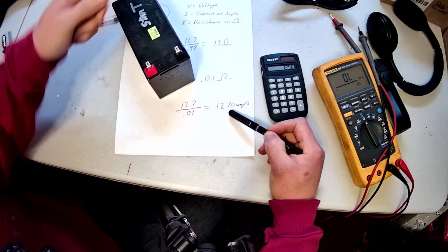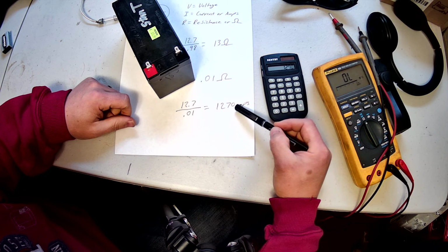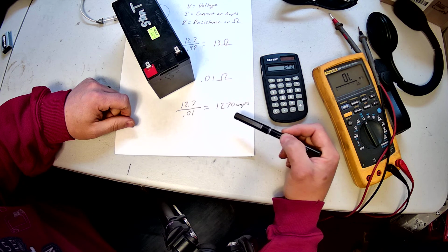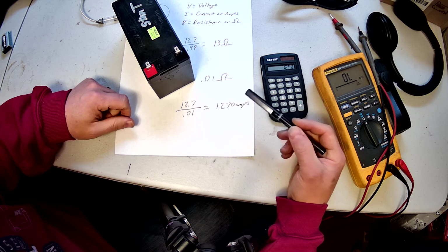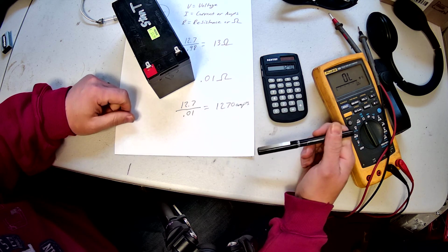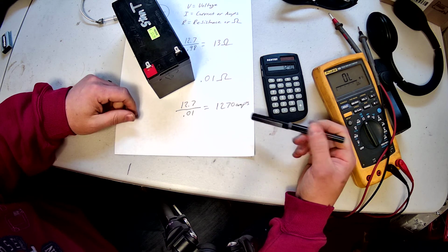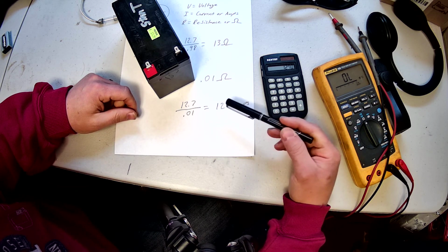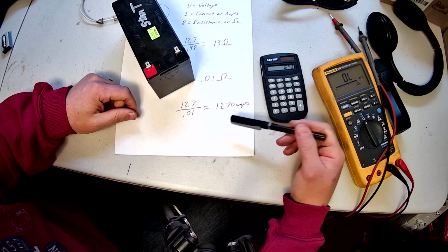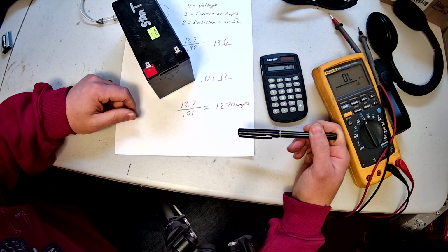And if you were to put that wrench across those terminals, you're basically going to pull that much amperage through there, which is a lot of energy, and you're going to get that wrench glowing red, or you're going to weld it. And this is the same exact principle that we use in welding class when we're using either the MIG welders or the arc welders or the TIG welders, is that we are short-circuiting the power, which creates a lot of current and a lot of heat, and that is enough heat actually to melt metal together.